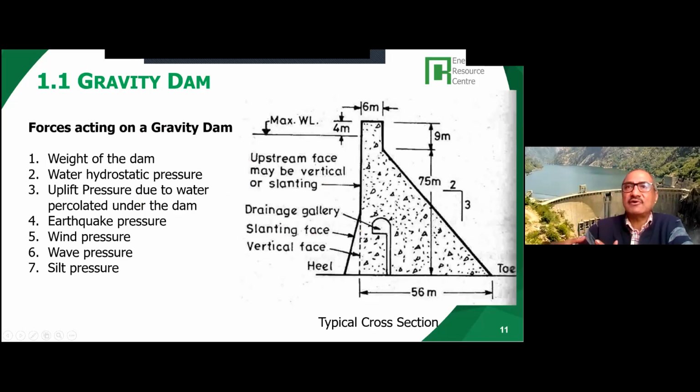So this is more of a software thing instead of really building, and you can have check dams along the catchment. These types of catchment improvement programs are done by the country and by the dam authorities also. So you try to reduce the flow of sediment, that is number two.